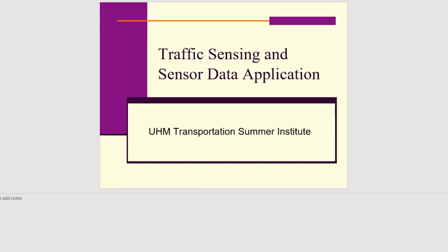This is the roadside controller. The controller has input output facilities and detection cards, and processes all the detection data. Decisions are then made and sent to the signal head to allocate the right of way, meaning the green indication, to the different approaches.